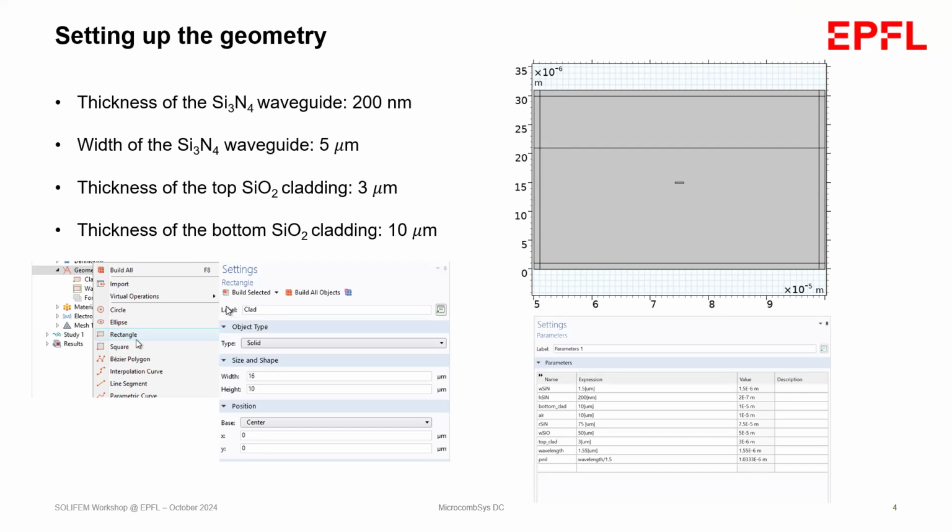I've specially chosen a thin waveguide because a thicker waveguide can be designed even for 1 terahertz. I just showed you Soliton work done with a 1 terahertz resonator, where the bending loss is not even high, so it can be assumed negligible. Hence, bending loss comes into the picture when the waveguides are thinner. Therefore, this can give you a better estimation.